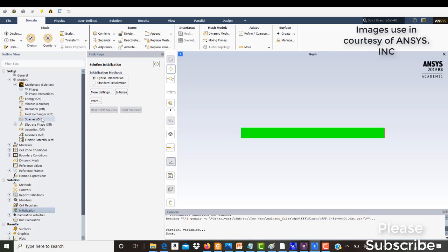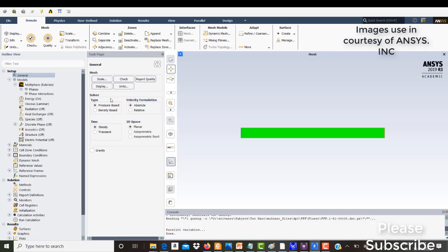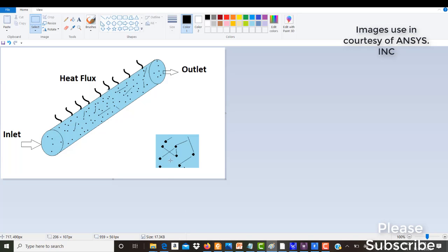Right, so when we go into Fluent, this is the general setup I have given. Here I will consider the steady state approach. The steady state approach is only practical or correct when the granular temperature is low. As I discussed previously, if the molecules are moving at a high kinetic energy, then there is no steady state at all, because it is transient and depends on time.